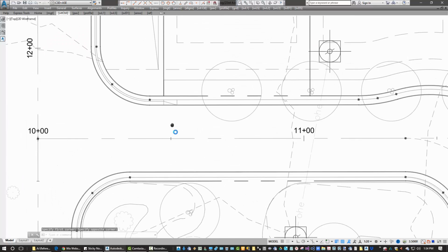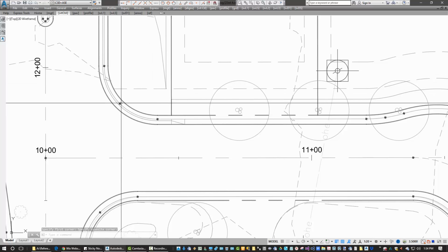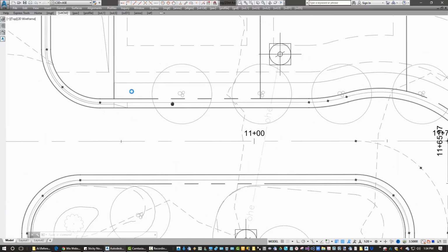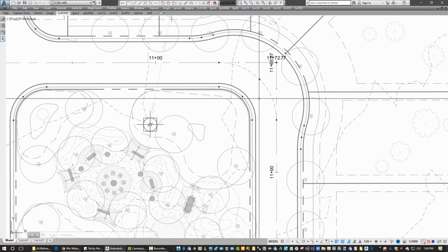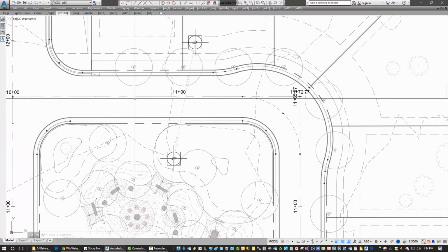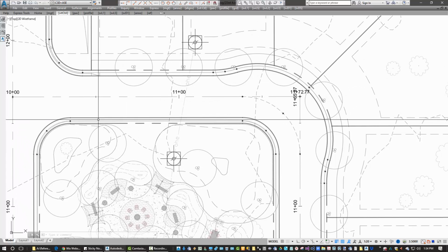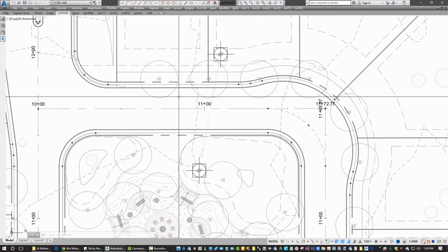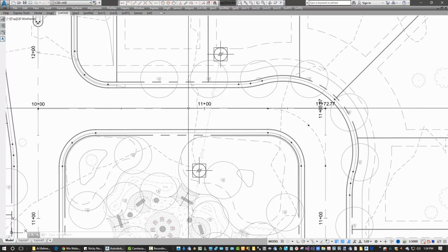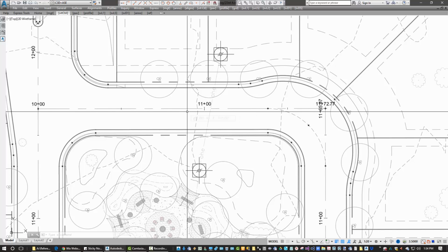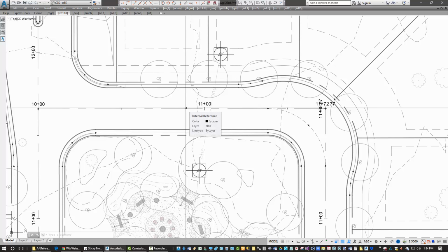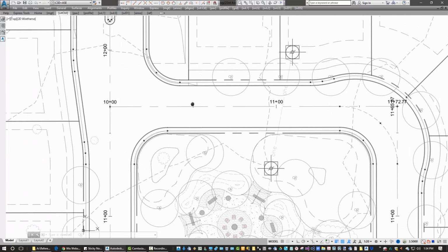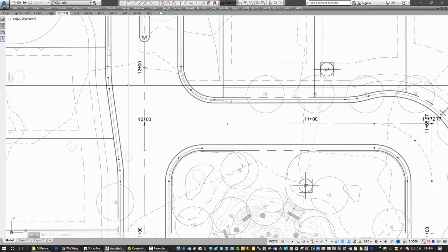And you can see our design markers here on the midpoints of the arcs along the curb control line of the base map control. And on each of the 3 alignment components in the corridors, the left, center, and right. And the markers are also attached to these alignments. So we can use these for paving feature design later. So after we've got the markers in, we can create flow labels. So as we elevate the markers, we'll be able to see where our drainage is going. So that's going to be our next step here.